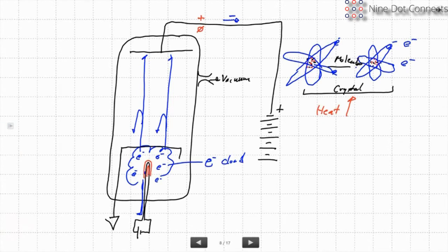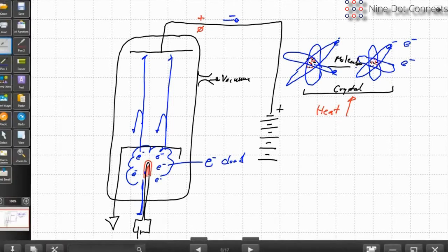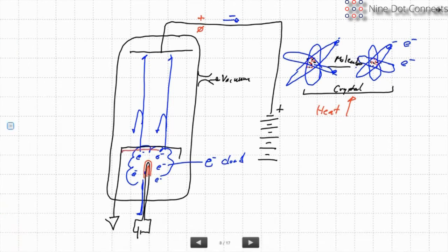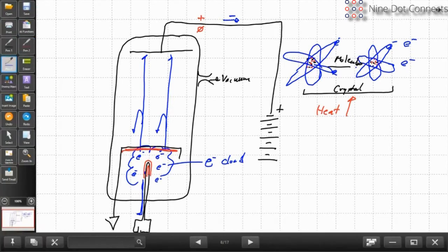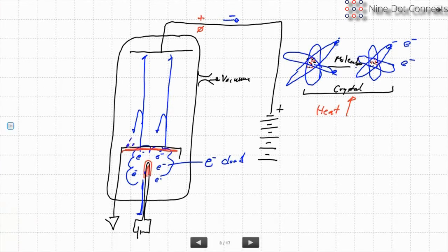And what would happen is it would get hot with respect to the heater because the heater would heat it up. And they also treated it with thorium. Now, thorium is radioactive. So the radioactive portion of that meant that it also wanted to throw out even more electrons. It highly ionized the surface. So the electrons coming out were a lot higher. The goal they were trying to do was to get a lot of electrons so they could get a lot of current flow so they could get a lot of power.